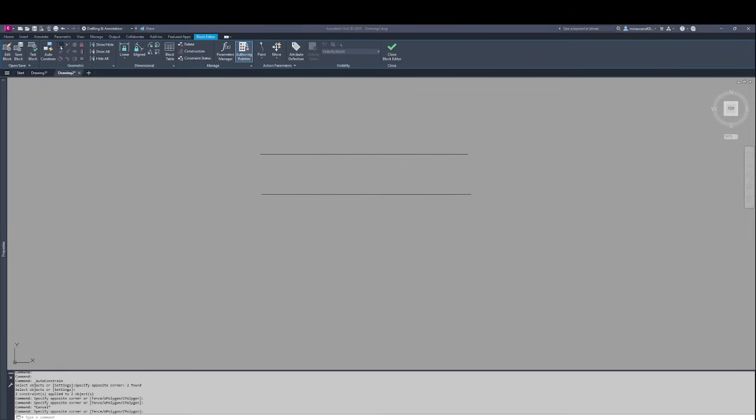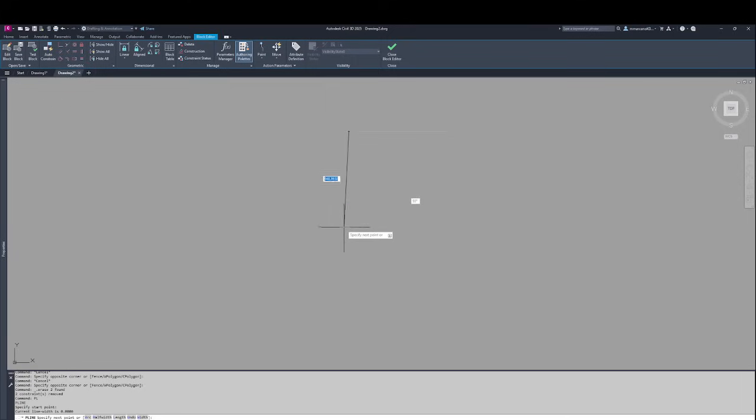Next we have our coincident constraint. So here we have two lines, okay? And so what I can do is I can select coincidence. I can select my first point, so let's say this point here, and then select my second point. And so if I choose, for example, this point, the midpoint, I can select that one. And notice that they snapped to each other, okay?